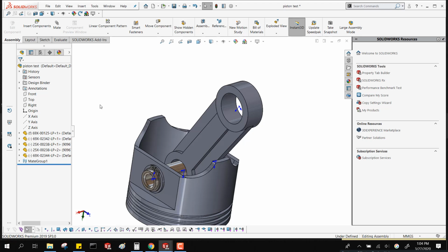They're fantastic for really keeping things organized, but I think right. And I typically will do, I love doing the master model for the enclosure, for all the plates inside, for all the stuff that's not moving. It's great because you're in there. But if you have something that's going to move, just don't put it in the master model. Just model it outside and then mate it into the assembly, or have some dummy part in the master model, just to sort of represent it, because otherwise you're going to get a part that keeps wanting to resolve to its location.